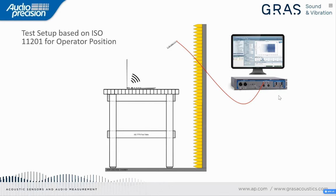And this is a setup that is based on the ISO 11201 standard. And this setup is used to measure the noise of the device under test at the operator's position. The ISO test table is once again used, and we are performing the measurement in a hemi-anechoic chamber.